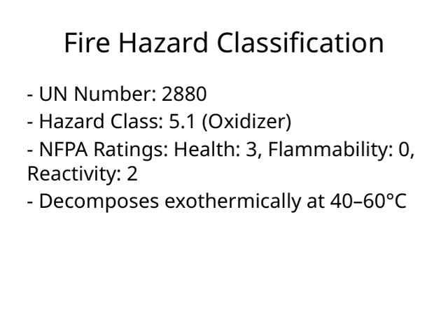The NFPA ratings provide a quick snapshot of the risks involved. This material has a health rating of 3, indicating that exposure could cause serious or permanent injury. Its flammability rating is 0, meaning it's not flammable under normal conditions, and its reactivity is rated 2, which suggests it can react with certain substances and needs to be stored properly.